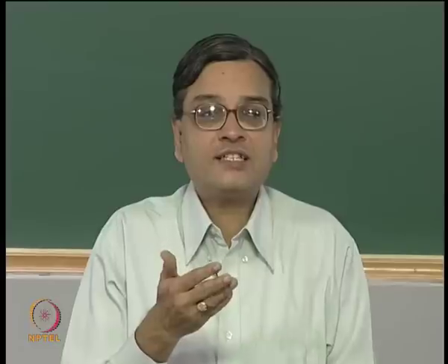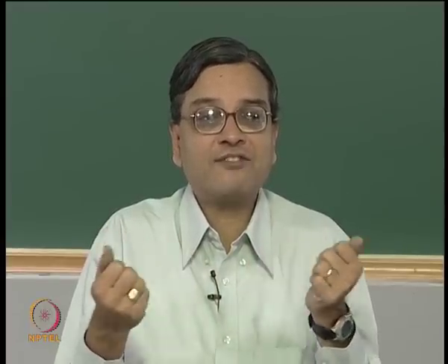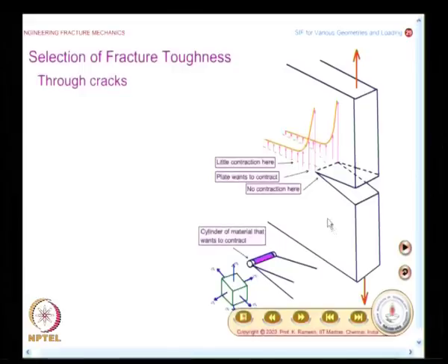So, in essence, in thick plates you have triaxial state of stress near the crack, and that zone is indicated here. So, in the case of crack problems, near the vicinity of the stress concentration, you could have under suitable circumstances a triaxial state of stress.